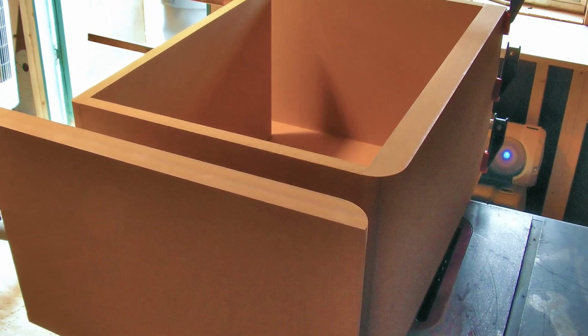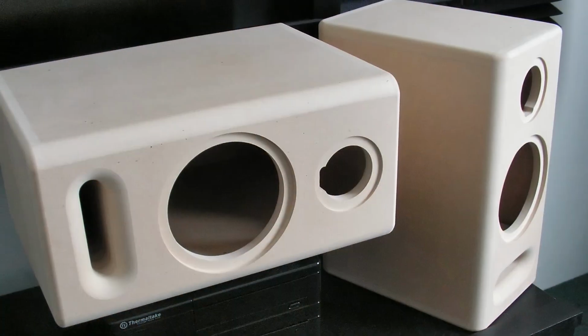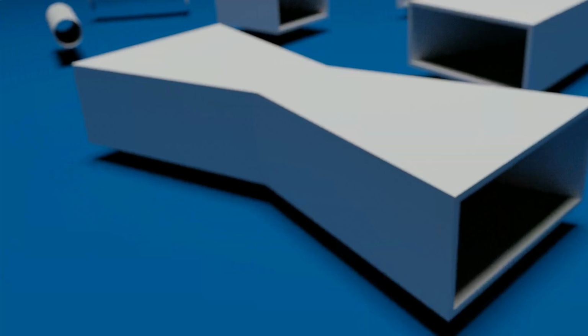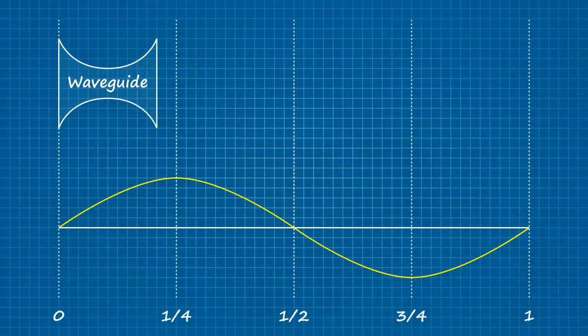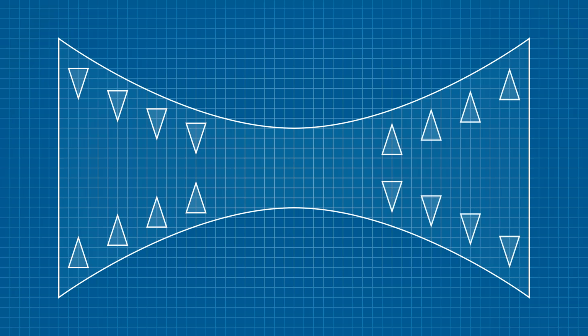For as long as I've done this, there's only ever been a small handful of projects actually relying on a broad flare at the end of the waveguide. So, building on this, let's have a look at compound tapered waveguides, or if you prefer, two horns joined at the throat. These are almost always going to be acoustically small, and as such, their operation is similar to that of a flared port, minus the linear section. And as you gradually compress, then decompress the airflow passing through, you still achieve an air mass, but with far less disruption at either end, which makes these ideal for high velocity applications.